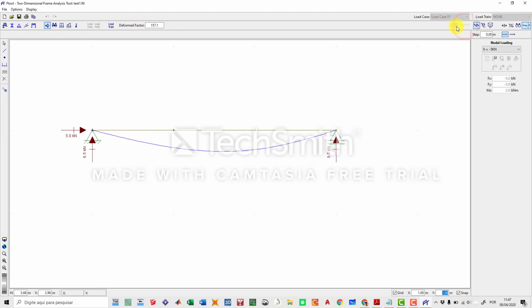And lastly, you can also see the displacement of your structure. Actually, this displacement is extremely exaggerated, but it is an example of how your beam is going to perform. Another interesting thing is that if you click on any part of your beam, you can collect information about that specific notch. So if we were going to assess the bending moments, if you click on any part of your beam, you can see the value of the bending forces and shear forces, etc.